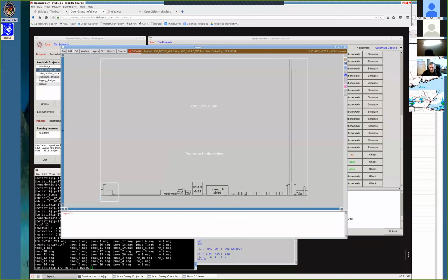So let me go back to that 200 by 300 area that I wanted, which is about there. Okay. If I want to fill that box with something, here I'm going to fill it with metal 1. I'm going to go over to my tools and click the middle mouse button to generate the layer, and that fills the box. Magic's idea is of painting on a plane, so they refer to it as painting.